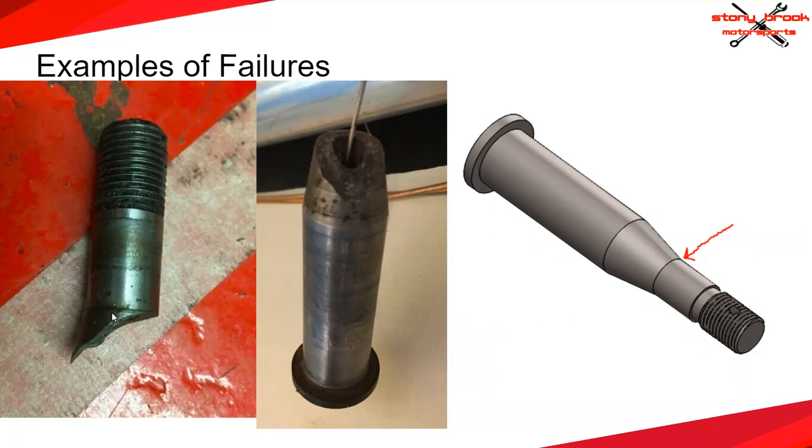down occurring. Essentially, at some point the car went a bit off track and hit something, and that hit went directly through the tire, and the tire transmitted the force onto the spindle. And the failure, you can see, starts basically right at that step down. It caused the piece to just shear and completely fail. So this is a lesson: you have to be careful not just with your design, but also with how you make the part, because in the end, you might not get something too ideal.